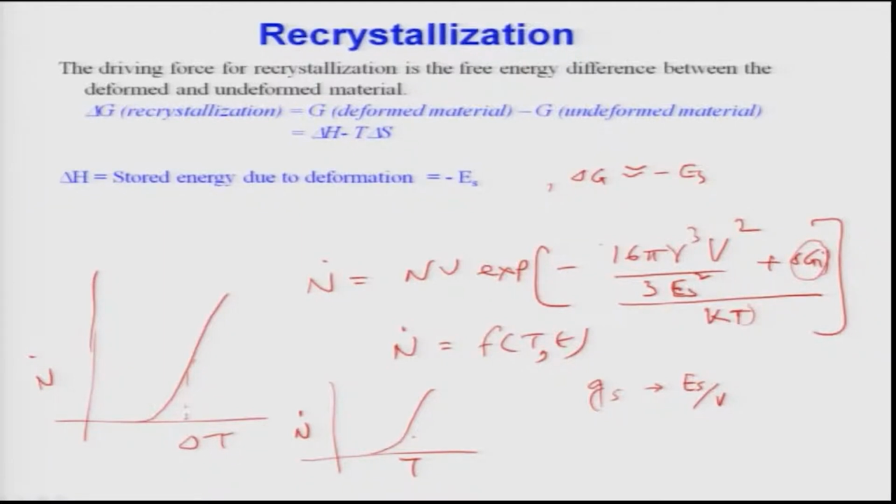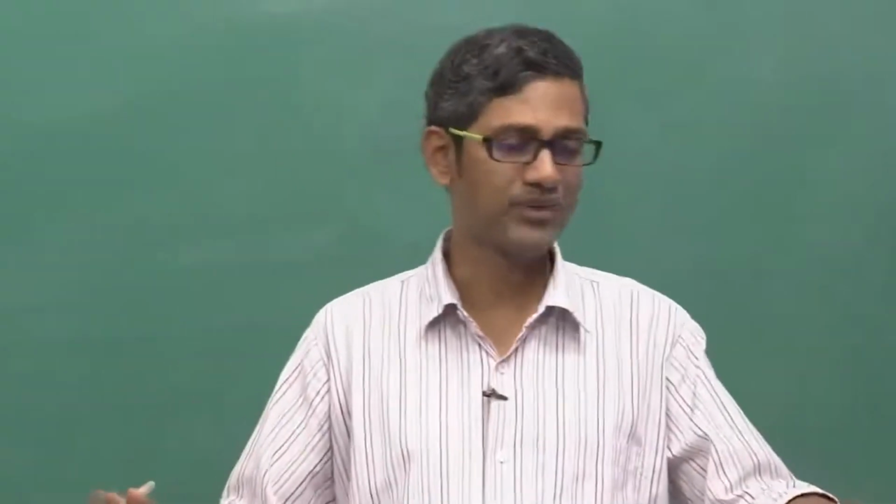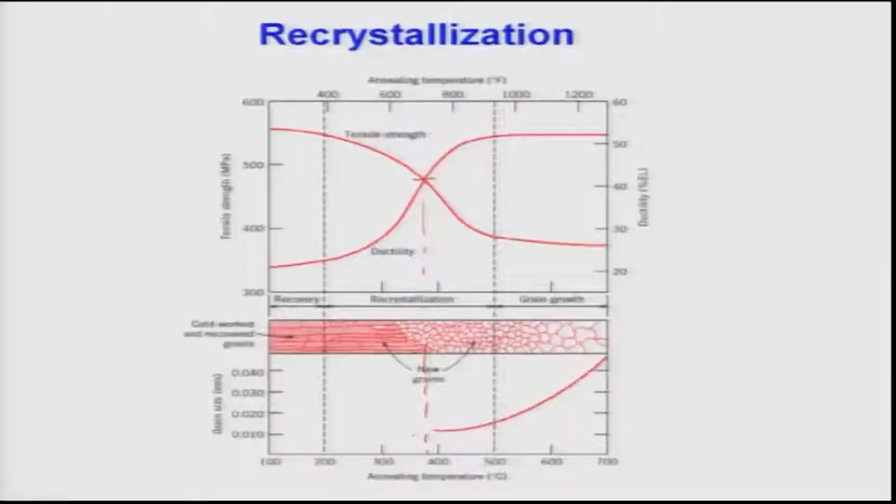That is one important aspect which must be remembered always. So, once the new grains form, the subsequent process is nothing but growth. The kinetics on which this whole thing depends is known as the Johnson-Mehl-Avrami type of equation. As I told you, Johnson, Mehl and Avrami, these three scientists developed a model, and this model dictates how the grains actually grow. We will discuss in a subsequent part of the lecture what this equation is.